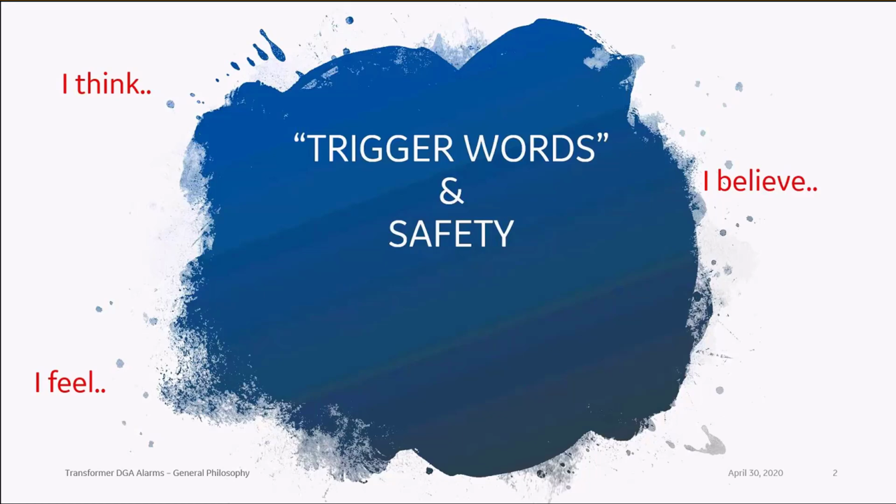And for those of you on the call that have done any investigating into this, you know that it doesn't take very much. It takes a lot less current than that to kill somebody under the right circumstances. So you just need some good, low body resistance. You apply 10 kV to that, and you could find yourself very easily not waking up again. So I've seen this test set blow holes in people's feet before.